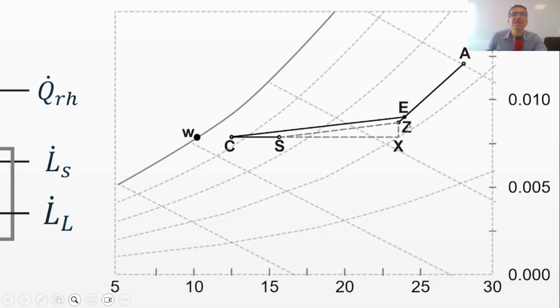So for typical summer conditions, the zone is set by comfort at 24 degrees and approximately 40% relative humidity, while the coil exit is maintained cold and near air saturation. So this is the question in the previous slide we were discussing. I was mentioning this part.